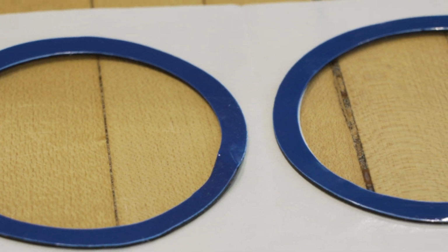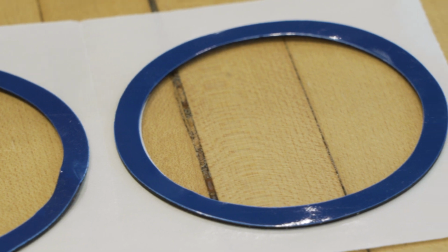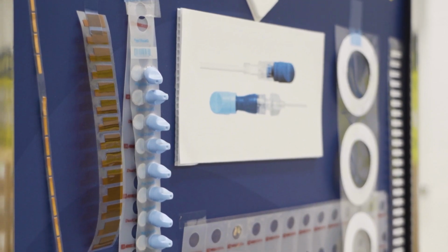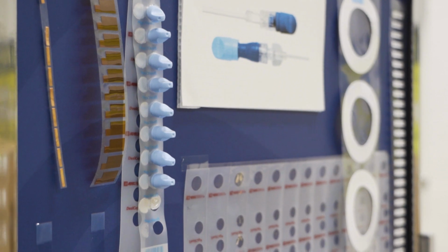A tolerance is a designated number that a part is allowed to be within. For instance, if you have a 1-inch circle, it's never going to be perfectly a 1-inch circle. It's always going to be 1.001 or 1.02. And so that tolerance determines how much over or under you can be within that 1-inch range.